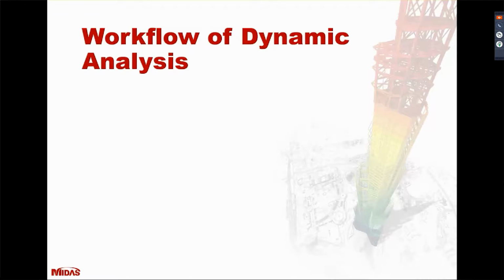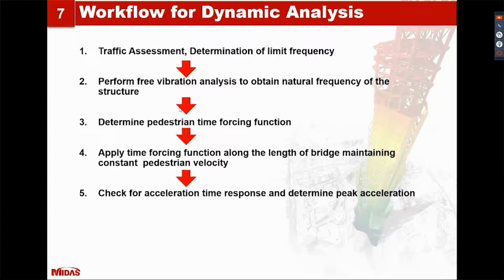So for the workflow of dynamic analysis for pedestrian bridges, first of all, we need to assess the traffic and determine the limit frequency. And then next, we must perform the free vibration analysis to obtain the natural frequency of the structure. Next, we must determine the pedestrian time forcing function, and then apply the time forcing function along the length of the bridge, maintaining constant pedestrian velocity. And then last, check for the acceleration time response and determine peak acceleration.